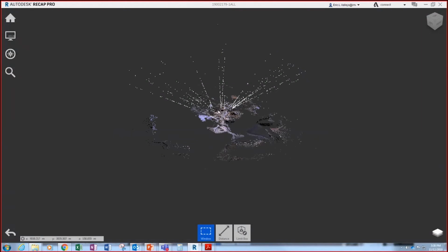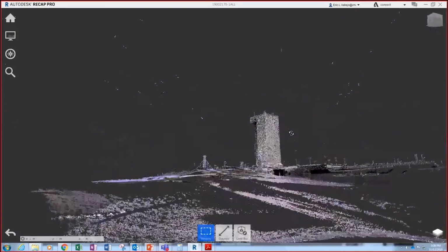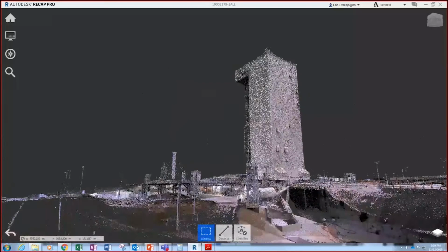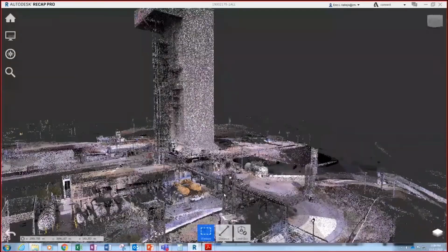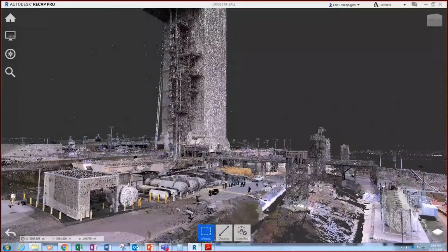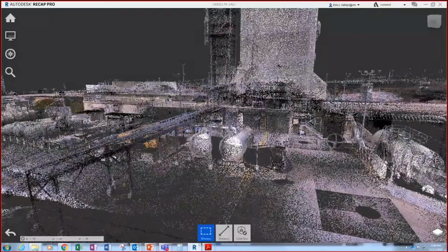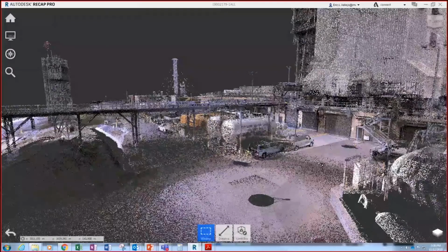It was just a traditional topo survey that we were doing, but the guys had some pretty complicated areas where they could use the SX10 to scan and collect data that I could in turn use to make our topo a little more detailed. There was a wall that the guys couldn't access because it was not safe. So they could scan it, and I was able to model that wall from the scan rather than putting our guys in a dangerous position.